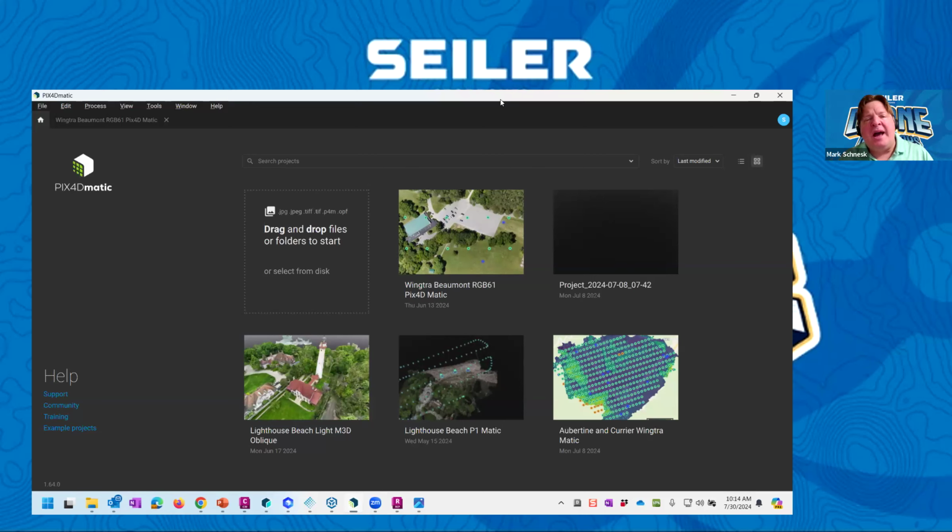We're going to apply ground control, something I haven't really touched on yet. We're going to get good data from the RTK, in fact stellar data from RTK or post-processed positions, but things could go wrong, and we could get even better results if we have proofed ground control. These are 3D points we've shot on the ground. We can really tie that data in in a very precise way. So to start a typical project, different software work different ways.